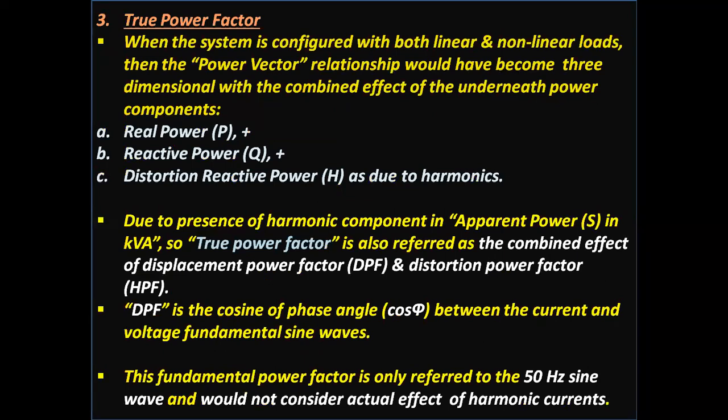True power factor. When the system is configured with both linear and nonlinear loads, the power factor relationship becomes three-dimensional with the combined effect of the underlying power components. One is the real power, another is the reactive power, and the third is the distortion reactive power due to harmonics.